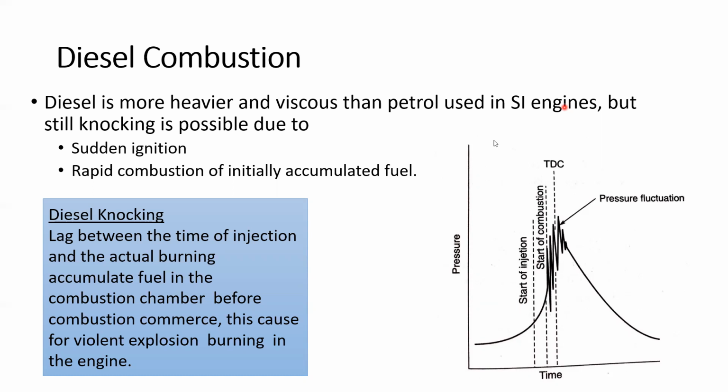So that's how we actually identify if there's knocking, or otherwise there's electronic equipment that we can use for this purpose, right? So in the diesel engine, if I come back, the same reason. After the fuel is injected, so fuel injection is where the ignition starts to happen, right? Once the fuel is injected, the pressure inside the combustion chamber rises even further. At a certain point, it starts to combust, right?